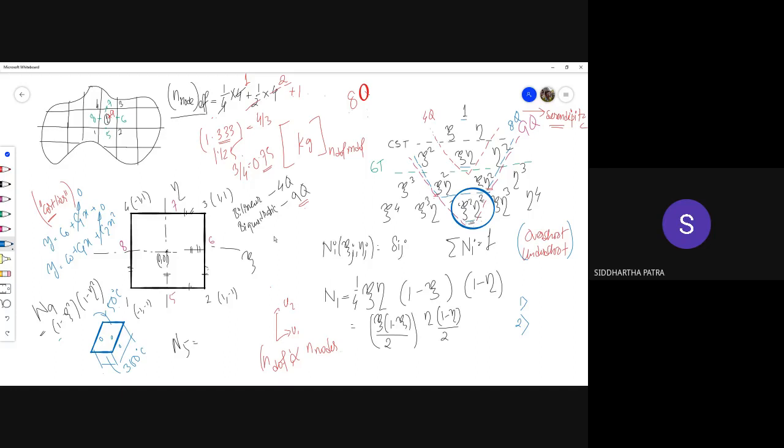Actually, if you move to 3D, the serendipity element kind of becomes obvious, because then you work with the 20-node brick element. The 8-node brick element would be the trilinear element, with nodes at the corners.